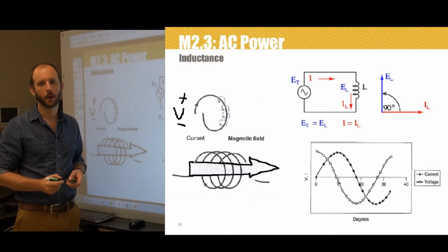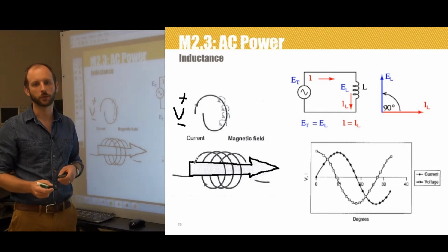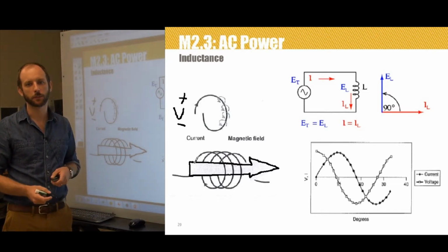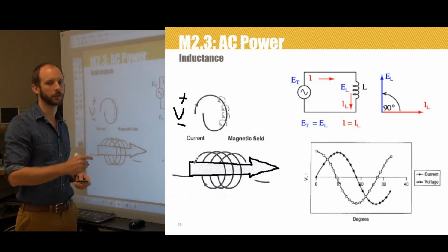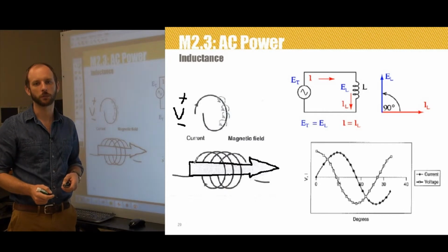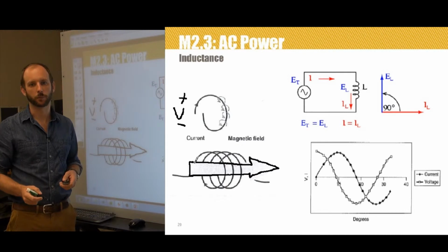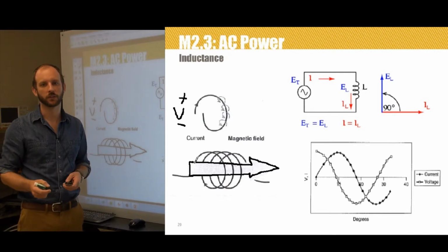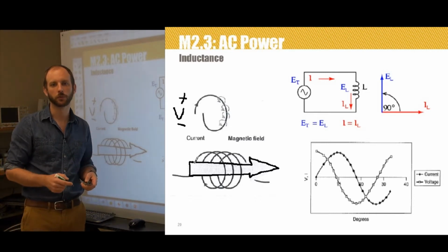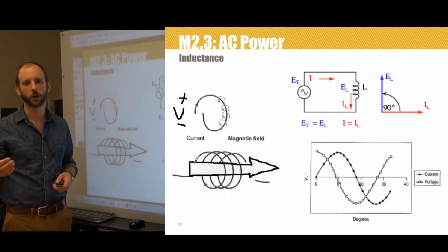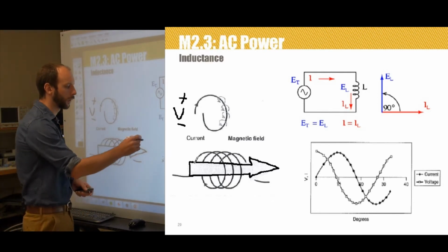of the circuit. Because the induced current in an inductor is related to the change in the AC cycle per unit time, the frequency of the AC cycle is very important. Again, the higher the frequency, the faster that magnetic field is changing, and therefore the greater the induced impeding current. The lower the frequency, the lower the effect, and the easier to pass current. We could think of this as a DC current corresponding to the extreme case of zero frequency, and therefore when a DC voltage is applied to an inductor, it will behave like an ordinary piece of wire after a brief charging.